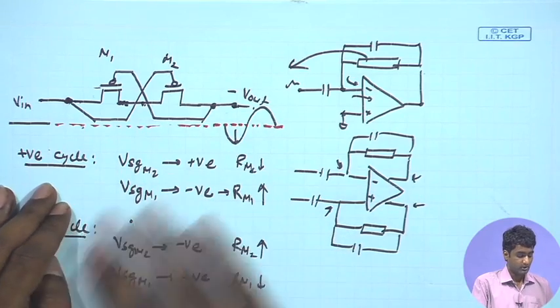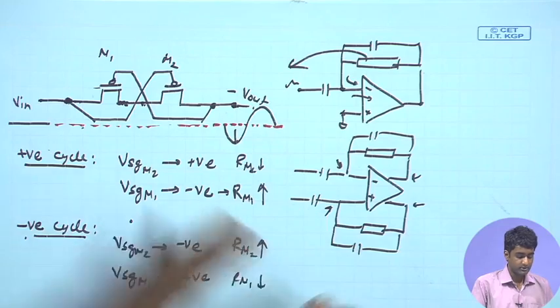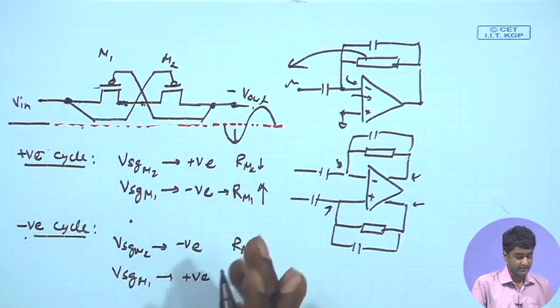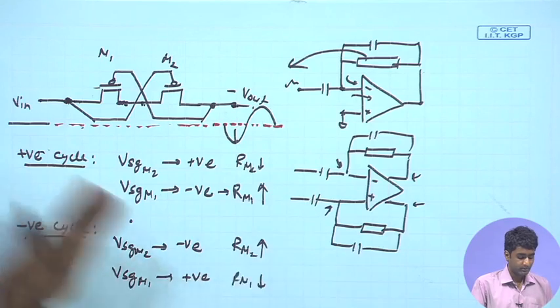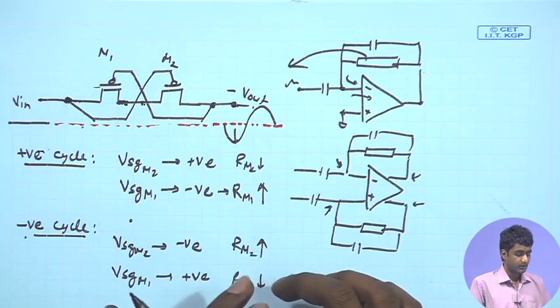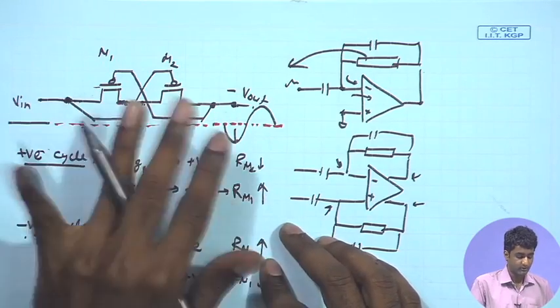of temperature. And in general, integrated circuits can be exposed to a wide range of temperature, even if it is for a specific application like a neural interface in this case. And likewise, process point of view also we can have significant shifts in the VT. It can be time dependent shift as well, which can shift the characteristics.